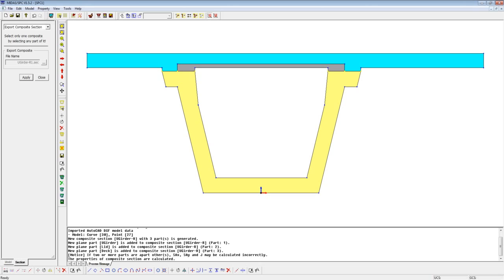Another question that is coming in. Can we use rigid links instead of dummy elements? Rigid links shouldn't be used because they are infinitely stiff, and what they really do is transfer the entire load from one source to another, which is not the true behavior of the deck, because at any given time the force is being transferred through the member whose thickness is this much only. So the section stiffness is overestimated if you use a rigid link to connect the two lines of the girders.